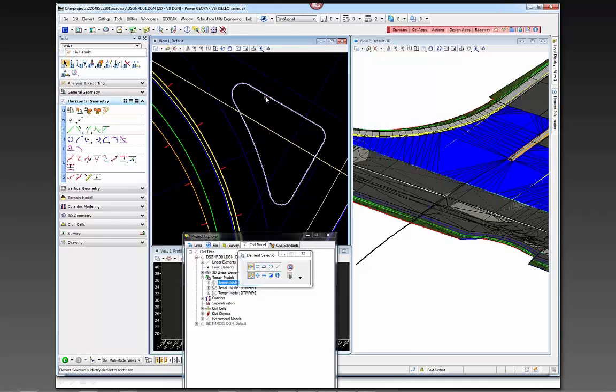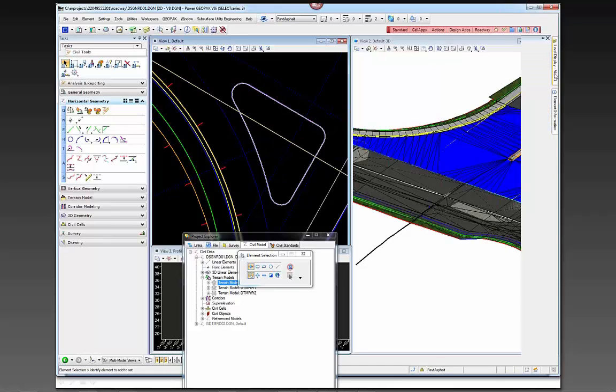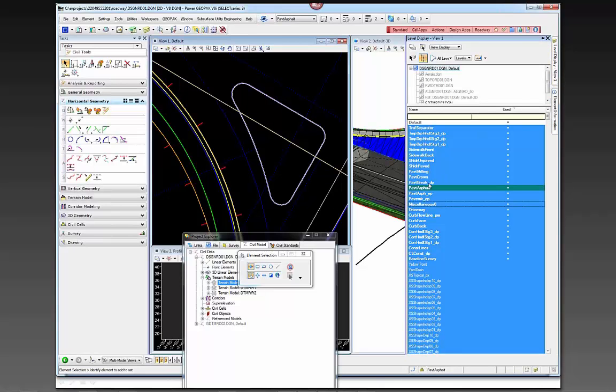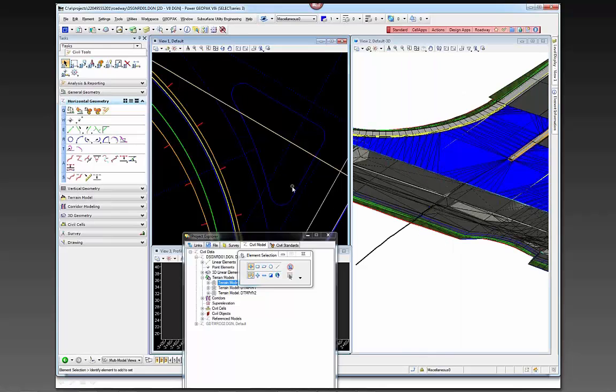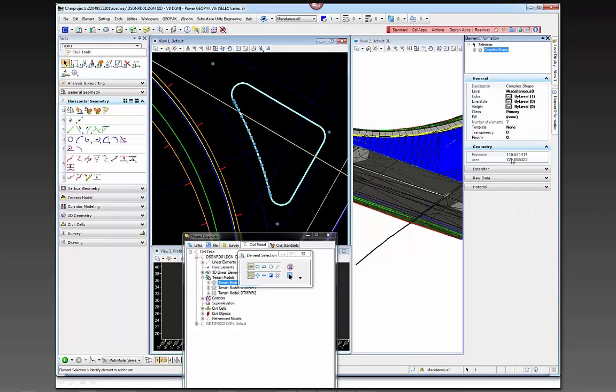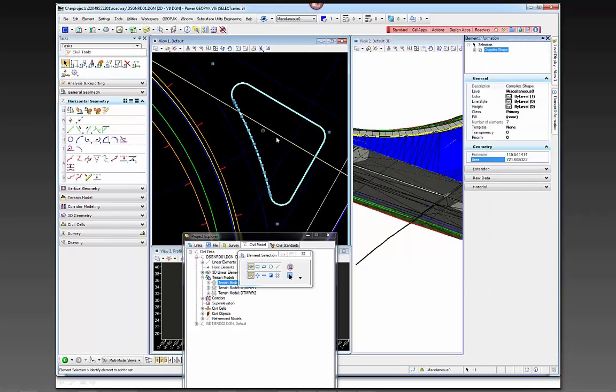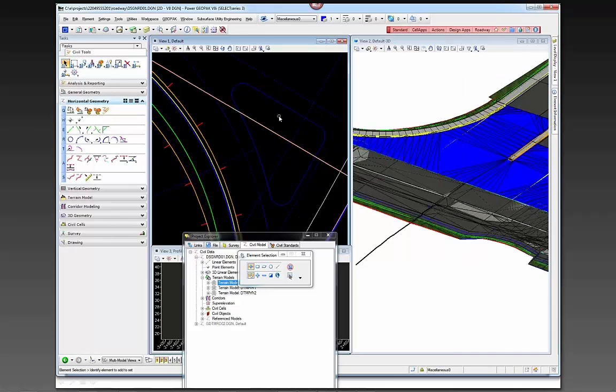And then I can turn off this level in this view for pavement asphalt, and I'll set active miscellaneous 0 so I can turn this, and now I have this shape that's out here. And this is what we use to figure out what the area of that was. So, you know, there's a minimum area, and that's a good way to check it, is once you've placed this civil cell, 2D civil cell, you can just go to the area and find out what that area is.